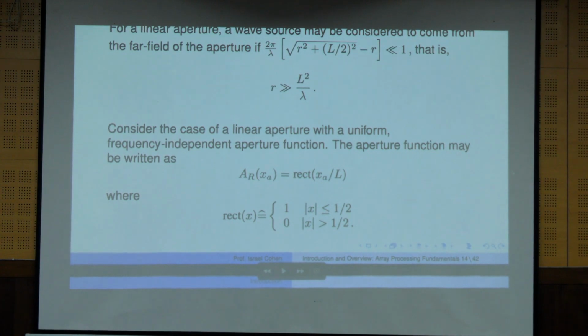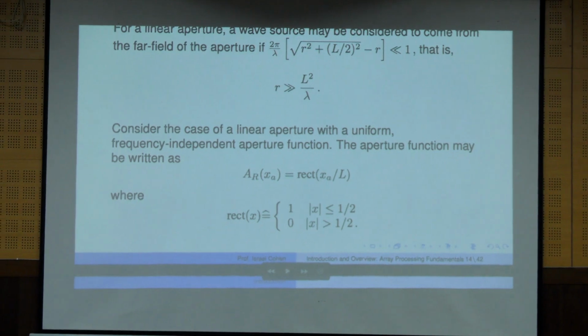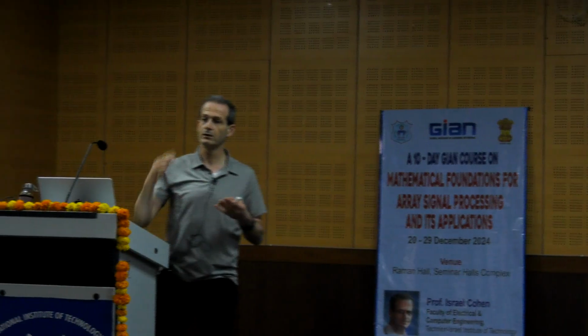of the target, but not the three-dimensional speed. Okay, so it depends on which direction it moves. So if it moves outward or forward to us, we can measure this speed in this direction. But if it's perpendicular to what we transmit, we don't know the speed in that direction because the frequency doesn't change. So we can combine. So you see, even something simple with simple assumptions, it's not that trivial. Okay?